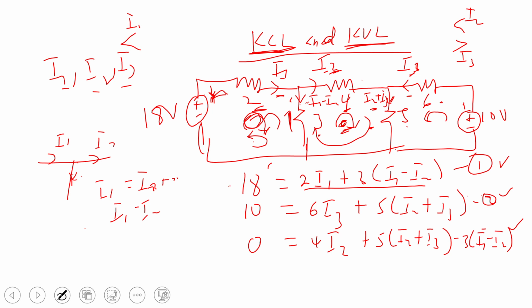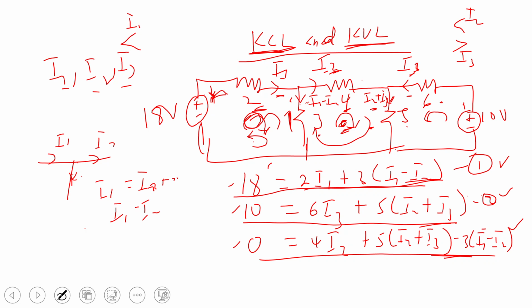Now, one thing is that if you're able to write equation 1, equation 2, equation 3, the rest is mathematics. So if you're able to write these three equations, you understand the concept of Kirchhoff laws. Most of the time, students make mistakes, especially when they are expanding this and this and this to arrange them for the simultaneous equation. That's when most students make mistakes. So as soon as you start making mistakes in those directions, you know that you have to check your mathematics most of the time, not because you don't understand the concept of the Kirchhoff current law and the Kirchhoff voltage law. So you have to expand this, and expand this, and solve it simultaneously. So basically, this is how to use that.